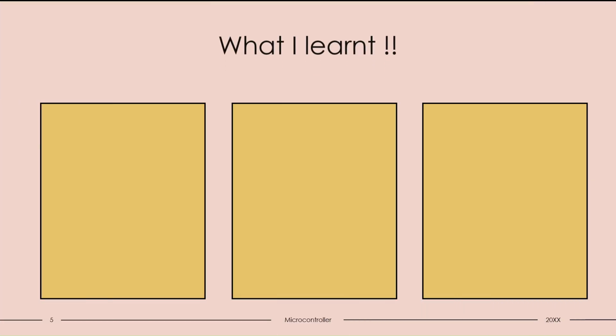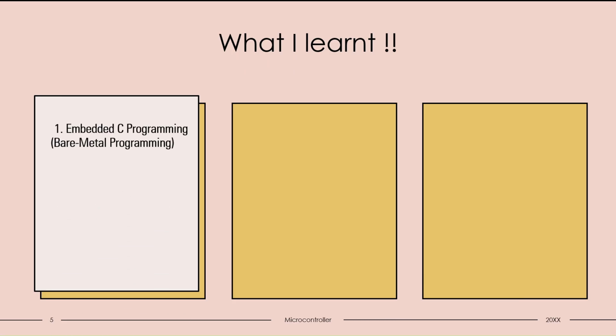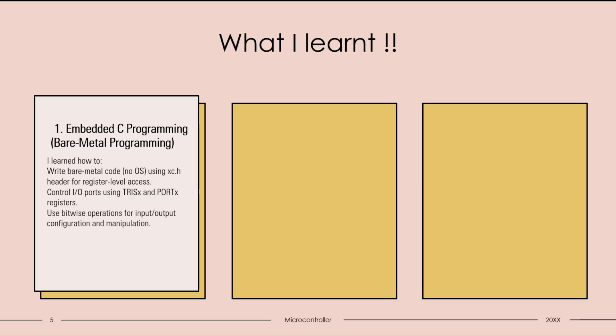Then what I learned in the microcontroller section, like embedded C programming. This was bare metal programming, as I learned to write bare metal code with no OS, using the xc.h header for register-level access, controlling input output ports using TRISx and PORTx registers, and using bitwise operations for input output configuration and manipulation. Create modular programming using init_config, main, while(1), the super loop. These were the various functions and macros we used, like delay macros, delay_ms and delay_us, for timing.